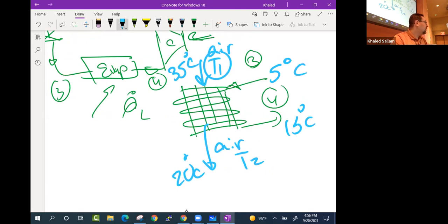right? And the water condensing on the coil, they are hugging the coil, right? And they really have quality time together. What will happen to that water sitting on the coil? It may subcool. So not only will it separate from the air, but the air that's at 20 and leaving at 20, the water will get subcooled, right?